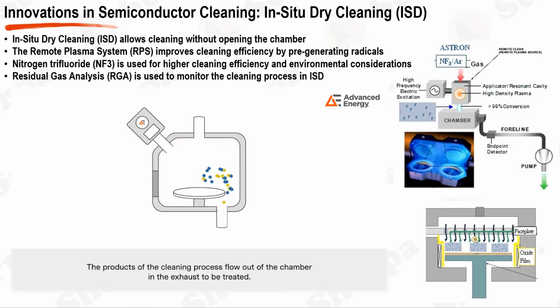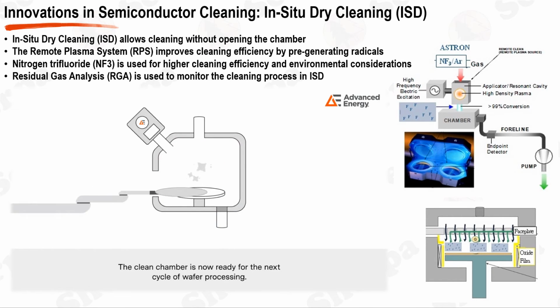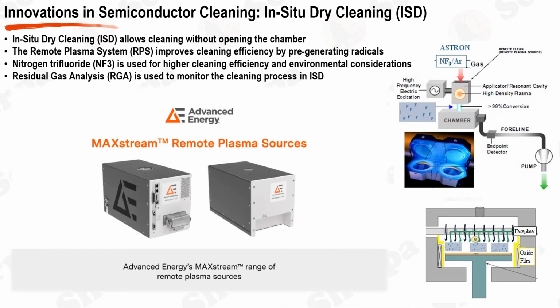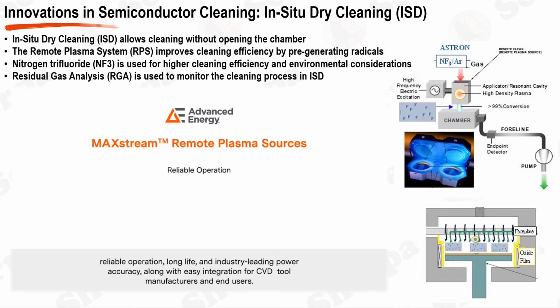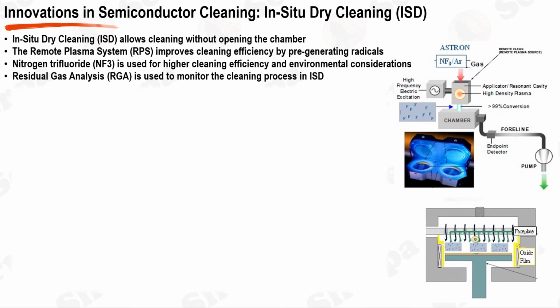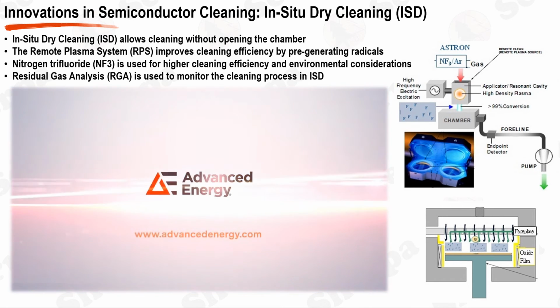An alternative cleaning approach that has lost favor is the use of chlorine trifluoride, ClF3, due to its inherent problems. ClF3-based cleaning is known to cause parts corrosion and has limitations in its application to various processes, leading to its phased-out use. The chamber's structure plays an essential role in the cleaning process. For instance, a rounded waveguide without sharp edges is preferred for preventing the accumulation of residues.